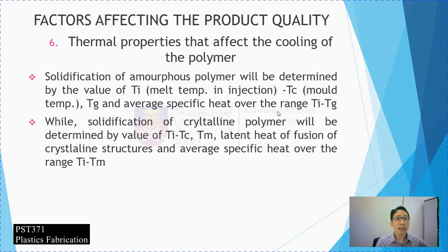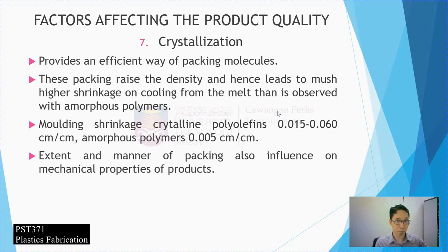Solidification of amorphous polymer will be determined by the value of Ti, the melting temperature in injection, Tc, the mold temperature, Tg, and the average specific heat over the range of Ti to Tg. While solidification of crystalline polymer will be determined by the value of Tc, Tm, the latent heat of fusion of the crystalline structure, and the average specific heat over the range of Tm.